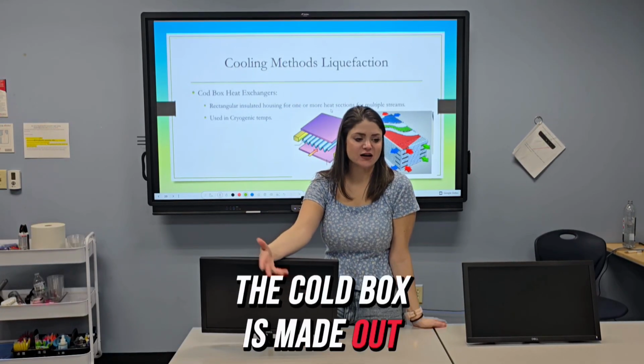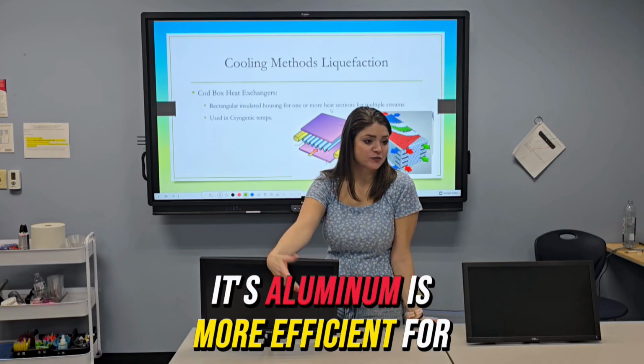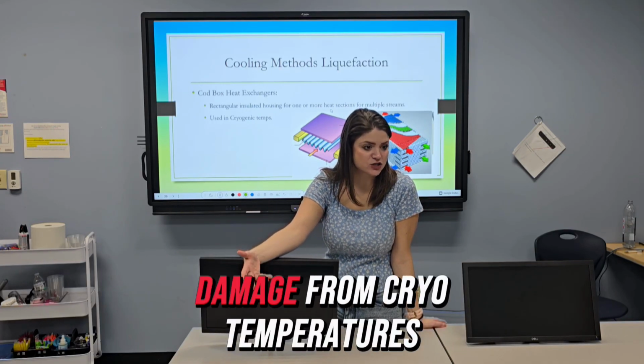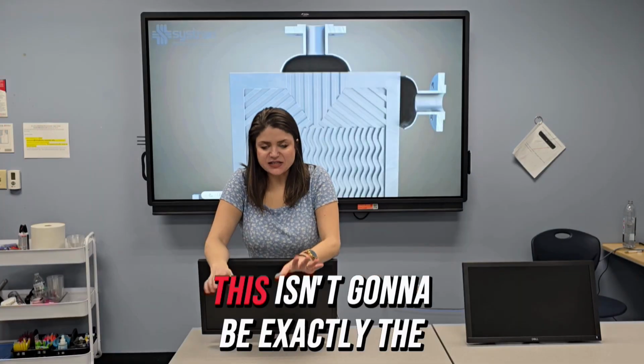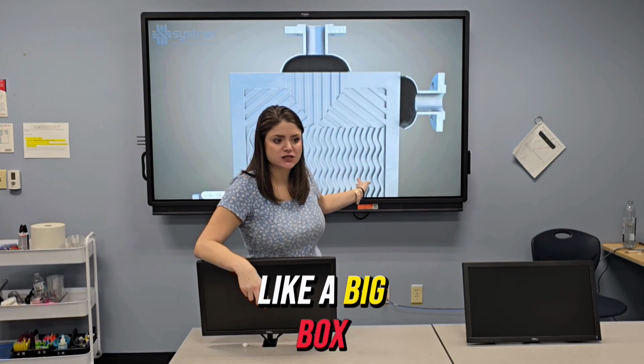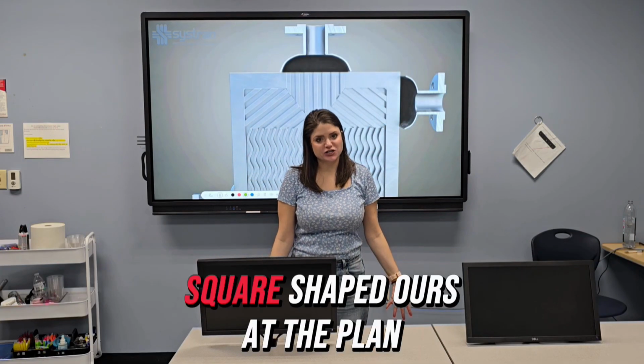The cold box is made out of aluminum. Aluminum is more efficient for heat transfer. Also, it is more resistant to damage from cryo temperatures. This isn't going to be exactly the same in every process. The cold box is going to look like a big box. It could be rectangular shaped, going up real tall, or square shaped.